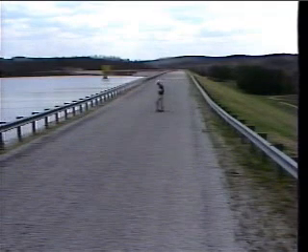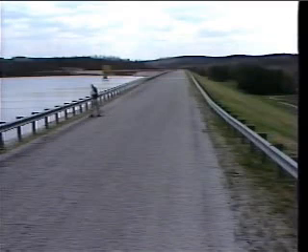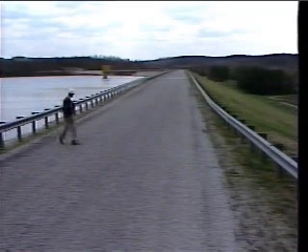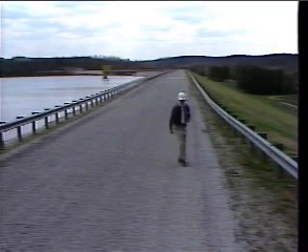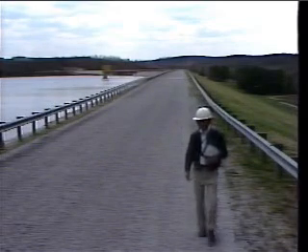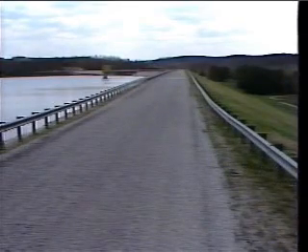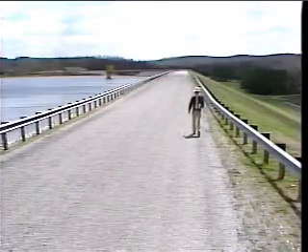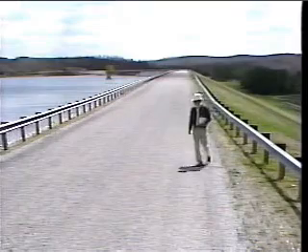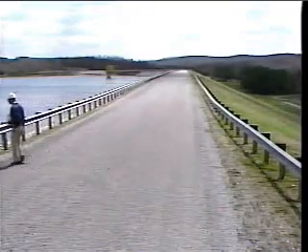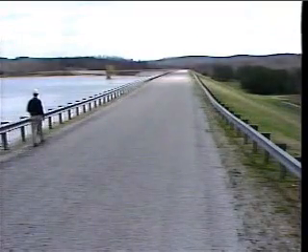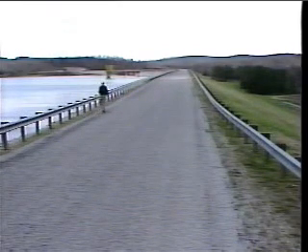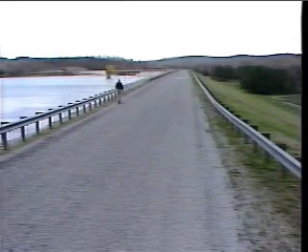As with the slopes, when walking the crest, it's important to look at every bit of the surface area. You can follow a zigzag pattern again, or you can walk the length of the upstream shoulder, then cross over to the downstream shoulder and walk its length. The shoulder is the contact point between the crest and the slope. The idea is to follow a logical pattern that will allow you to examine the whole crest area in detail.